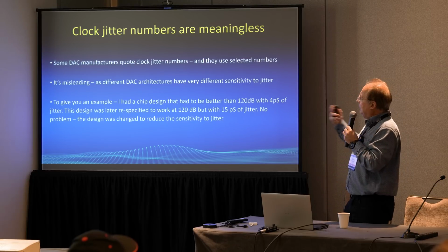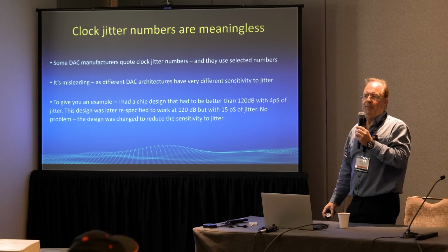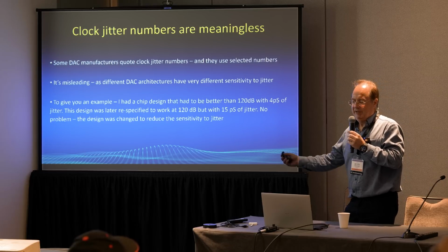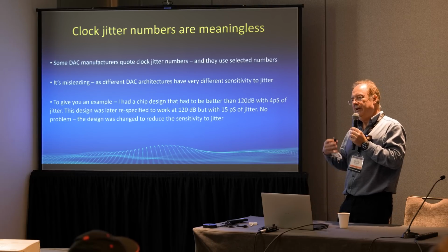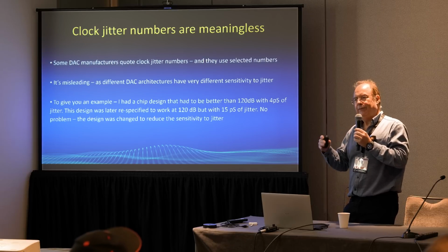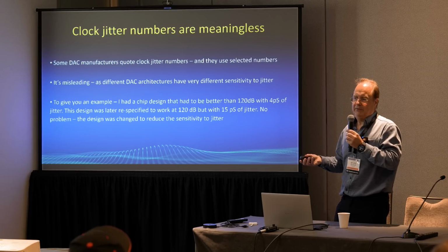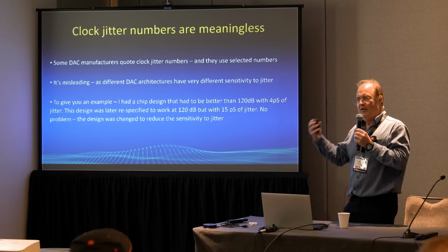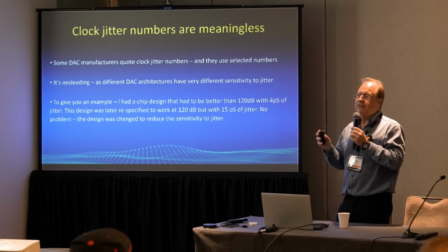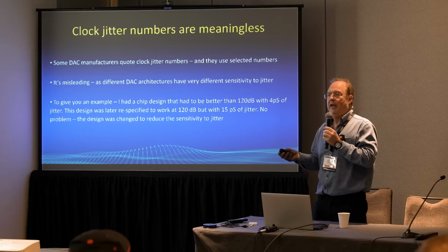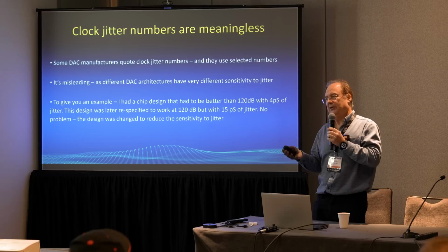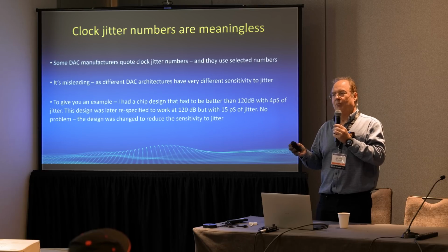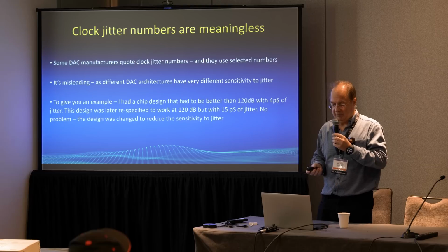So when you're buying one of my designs, it's my intellectual property. So firstly, I just want to introduce clock jitter, because a lot of people talk about femtosecond clocks, and therefore a femtosecond clock must be better than a picosecond clock. This is meaningless, and the reason it's meaningless is because different DAC architectures have different sensitivities to jitter. So it really makes no sense. You need to be talking about the DAC architecture, not the jitter numbers. The jitter numbers, they normally quote a cycle-to-cycle jitter, and that only tells you half the story, because in terms of sound quality, that is the least important problem. It's the low-frequency jitter characteristics, which they don't talk about, and that's the thing that actually changes the sound quality.